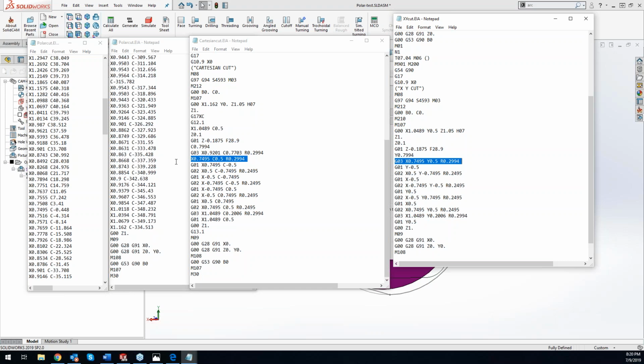And if you've got this G12.1, I believe most manuals call it polar interpolation, then yeah, definitely use that, because it's going to keep your code nice and short. You should be able to look at this code, and it's going to look very similar to what you're used to in XY programming, and much easier.